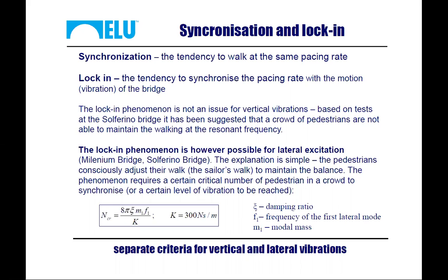So whereas the vertical vibrations are a question of comfort, so serviceability limit states, the lock-in phenomenon generated for lateral excitation could be a question of ultimate limit states. It can lead to synchronized motion. It can lead to very high vibration values, resonance, and it can damage your structure.